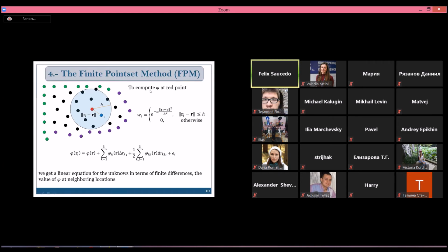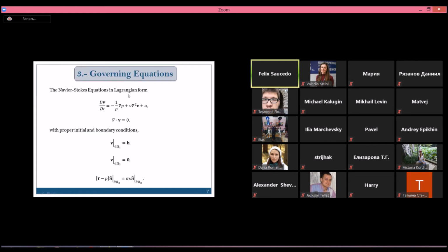Oh, okay. Yes, when you have differences between the properties, for example, this occurs during the solidification. During the solidification, we have a mushy zone that is like the transition between a liquid material and solid material. So here we have a deep change, for example, in the viscosity. And also we have a little change in the density. The little change in the density is not too critical, but the deep change in the viscosity is something that you need to take into account. In this case, I will go back a little bit. This equation that we have here, the Navier-Stokes equation in Lagrangian form, is not the correct form for that problem, because here...